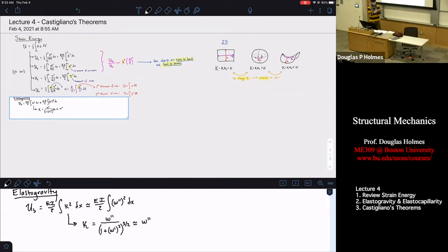If we can say that it'll bend into an exact circle, then we know our second derivative, then we know that the radius of the circle, which is equal to 1 over kappa, will basically be the length squared over your deflection.